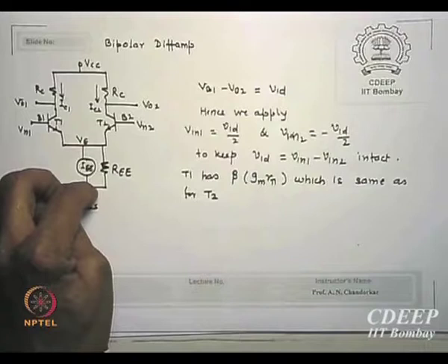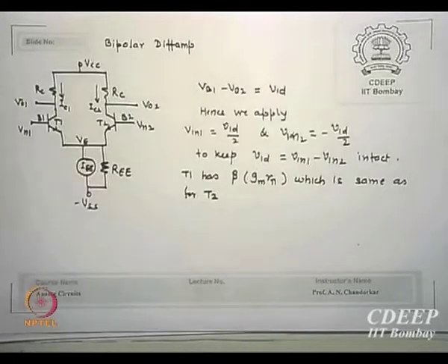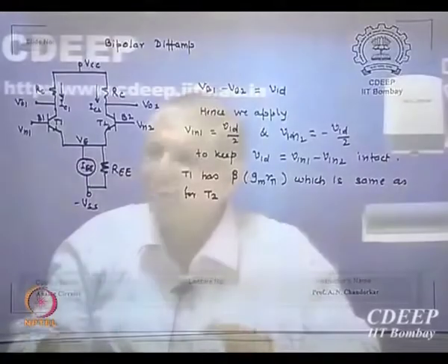In mine, I normally neglect these resistances in analog: RC, RB, RB dash and RS or RE. They may be used in case you want accurate analysis. In analytical work I think they are very minor. When you solve in SPICE, they will automatically be built in, so you don't have to think, they will come there in the model, and they will take care of themselves.